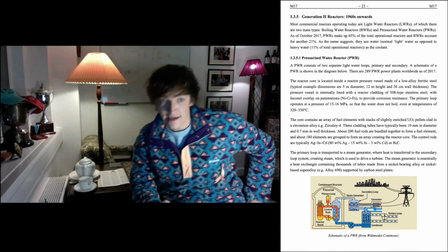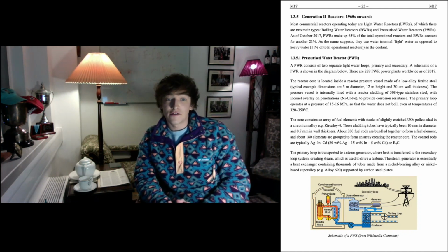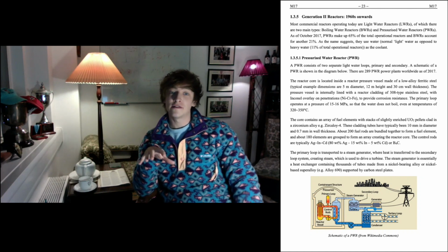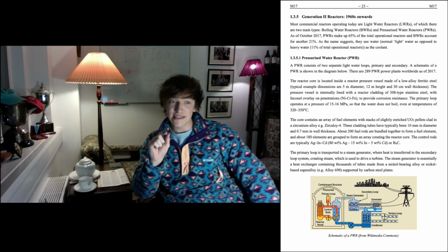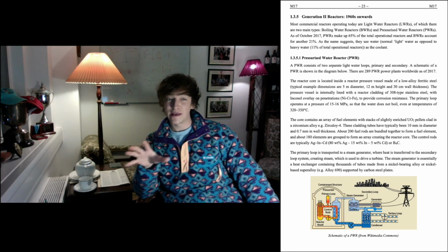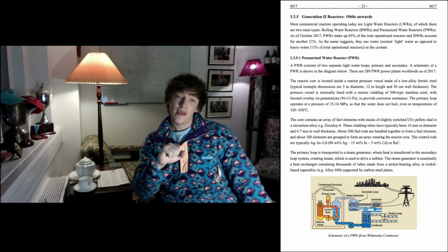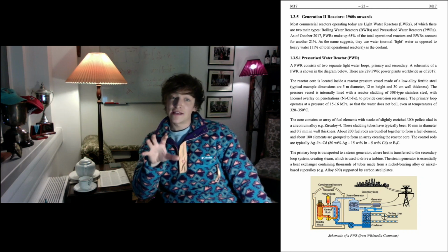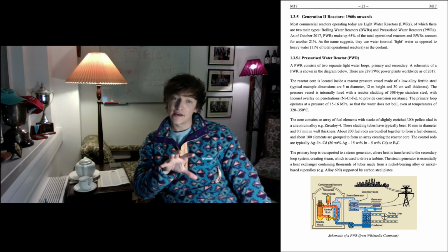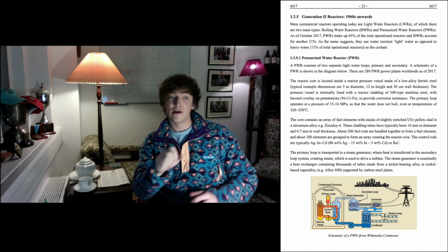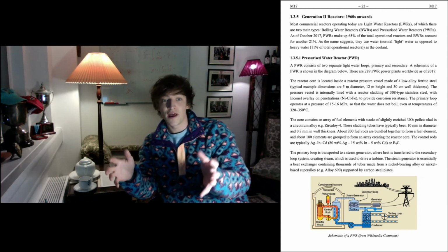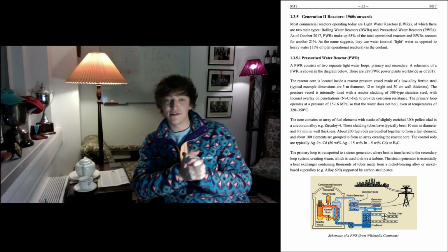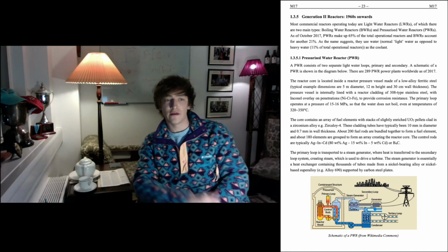Now, if you look at the steam generator, in a similar fashion to our Magnox reactors, the PWRs have water that's circulated across thousands of tiny steam generator tubes. And those tubes are typically made of a nickel-based alloy called alloy 690. And what these tubes allow is the transfer of heat from the primary circuit to the lower pressure secondary circuit, where steam is raised, which flows round to a turbine, just like in a coal plant, which is attached to a generator which produces the electricity that we can then distribute across the electricity network.